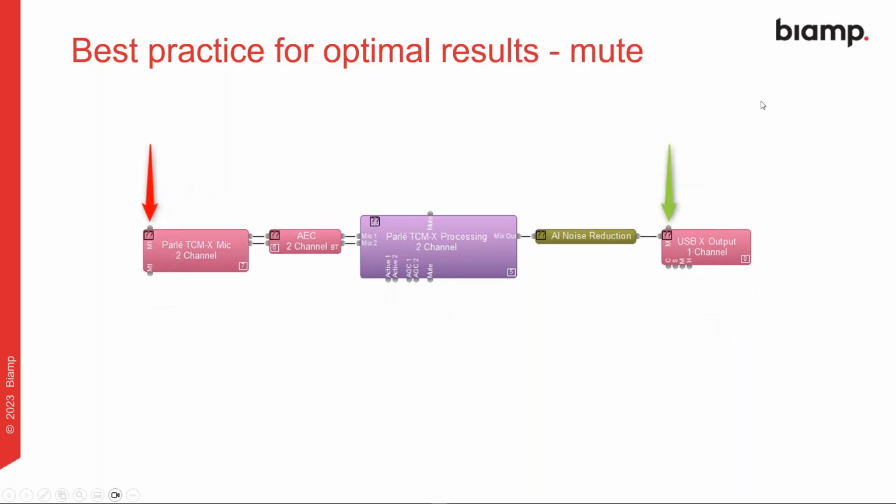This is a really minor point, but something I like to point out. Where do you mute your microphones to the far end? And this applies not only to AI, but also to AEC. You could mute them at the input, but the problem therein is actually, while they're muted, the AEC processing is not getting any signal with which to act on and converge on, and the AI isn't either.